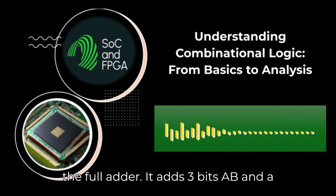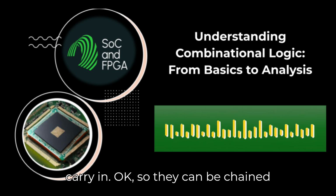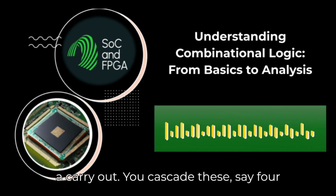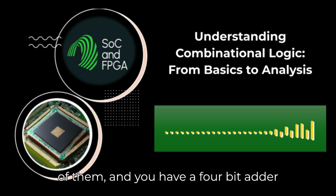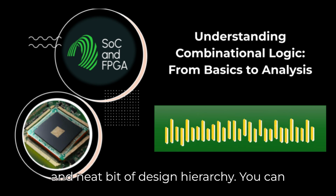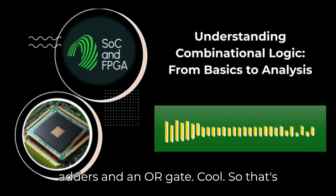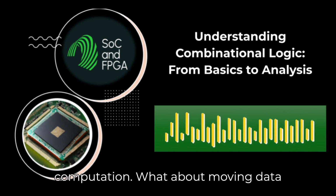Which leads us directly to the full adder. It adds 3 bits, A, B, and a carry in. Okay, so they can be chained together. Precisely. It produces a sum and a carry out. You cascade these, say 4 of them, and you have a 4-bit adder. And, neat bit of design hierarchy, you can actually build a full adder from 2 half adders and an OR gate. Cool, so that's computation.